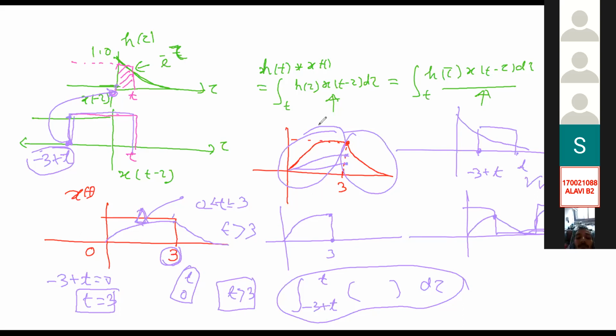But by using simple convolution, you cannot do that. The reason is that when you are starting this second phase, your capacitor can have RC values so that it will be discharging slowly rather than going to 0. Then this value is coming from your previous input, not from that input. So at this time, this value will be acting as the initial value for this portion of your pulse, okay? In order to incorporate this in your equation, you need to solve the differential equation.